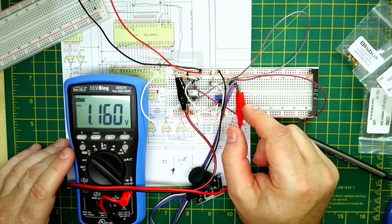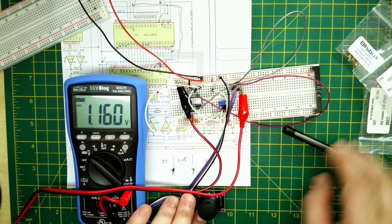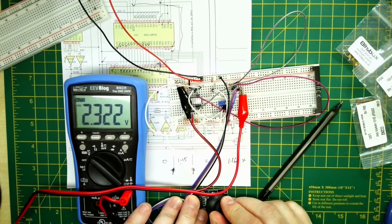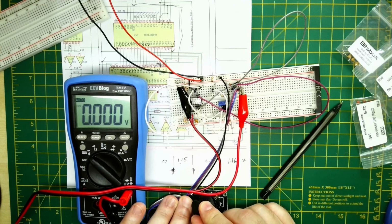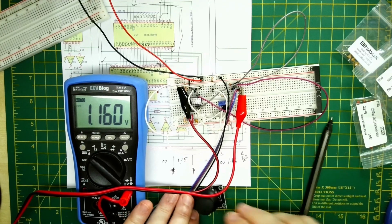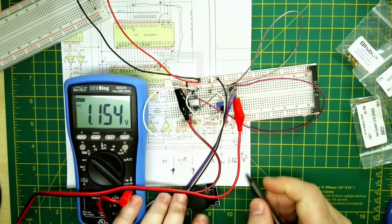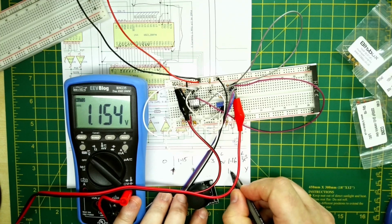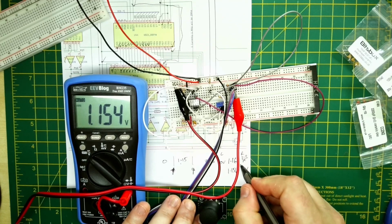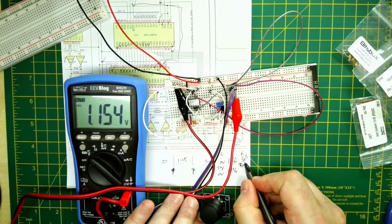I've got the voltmeter now on the grey lead, which is the X one, and you can see the center point voltage is about 1.16. So let's make a note of that: 1.16, that's X. If we go to the right, it goes to about 2.3 volts. If we go to the left, it goes to 0 volts. So left is 0 volts, right is 2.3. Then if we put this on the purple, which is the Y component, you can see Y is about 1.154. If we go to the top, we get 0 volts, and bottom, or down, is 2.3.